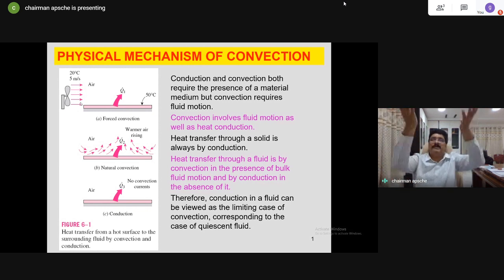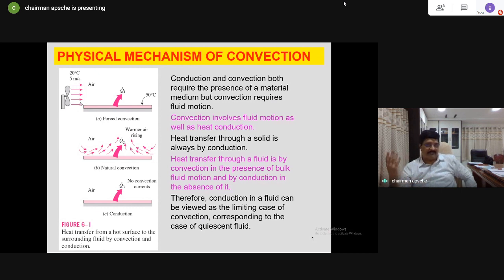Hot air vertically moves up towards the roof of the room, and when you provide a ventilator right on the top corner, you are paving the way for the hot air to escape, and therefore you are creating lower temperatures. I don't know whether the people have studied natural convection or not, but with their practical exposure they have created those things.